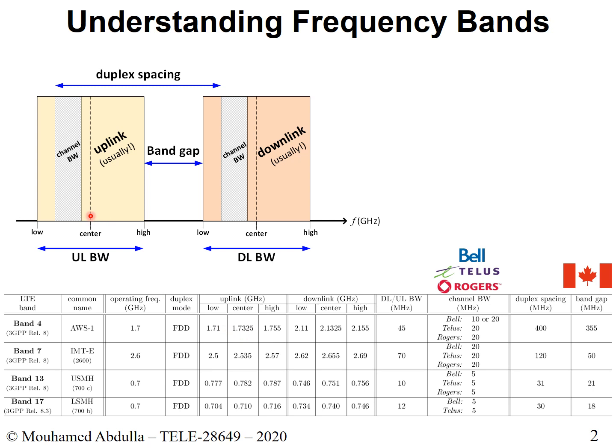So the lower end for LTE mobile communication for us, when you do an uplink, right? When you do an uplink, the lower end for the frequency is from 1.71 gigahertz in band 4 to 1.755 gigahertz. How do you find the center frequency? Or is it important to find the center frequency? Sometimes it is, and that's why we find it, but this is not necessary. This column is not necessary. You could forget about this column. I just did it because sometimes it's useful to know what your center frequency is.